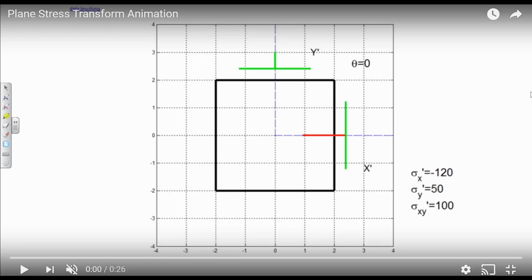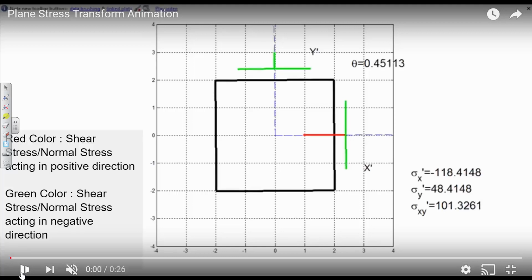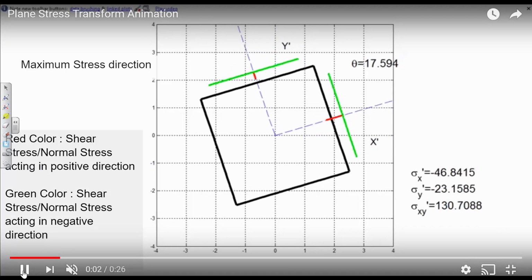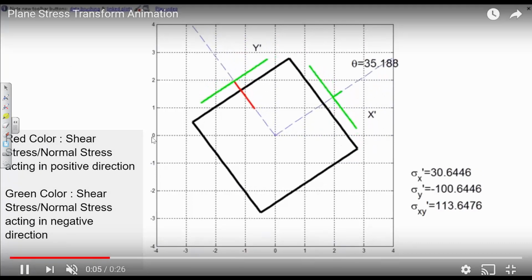And that's this. And then you start asking the question, well, what happens if I take those section cuts and I start changing the angle, okay? Well, you agree based off what's in that box that if I have a state of stress like this and I cut it at a different angle, I'm going to get another state of stress, right? So what this animation did, this is actually a really brilliant animation. They started rotating the box at given angles, and for every angle computed a new shear stress. So watch this. Watch what's happening as you rotate the angle. See what's happening? The state of stress changes.